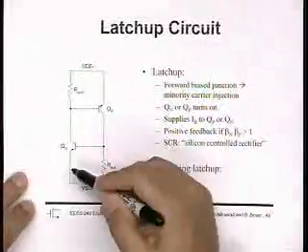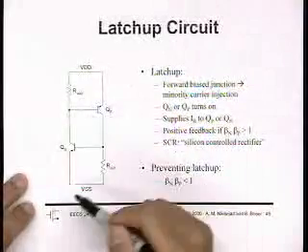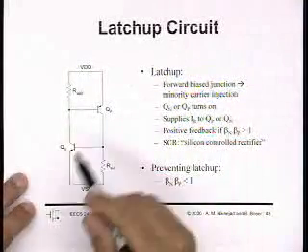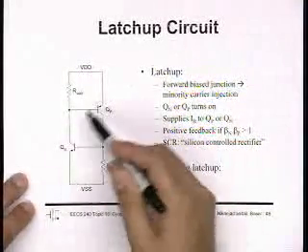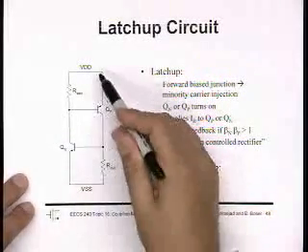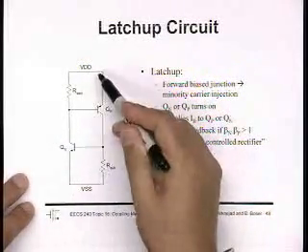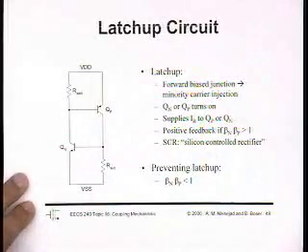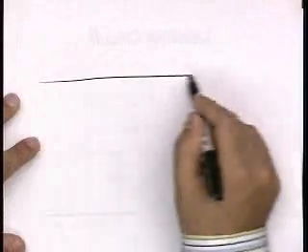Usually latch-up is explained with this equivalent circuit. Say, okay, I have this positive feedback, this is an SCR. If I have enough current gain in my devices, then this thing will latch. Positive feedback will start, and this will just short VDD to ground. Okay. There's perhaps an easier way to understand latch-up, and let me see if I can just explain that to you guys really quickly.